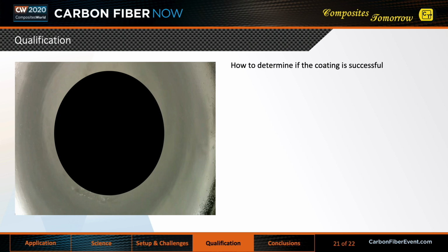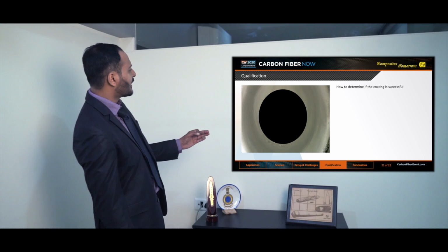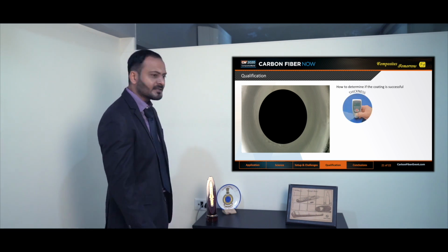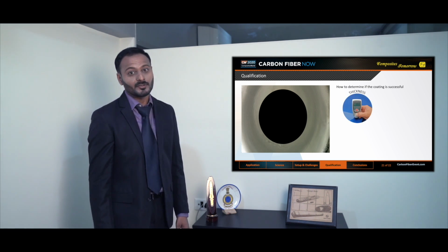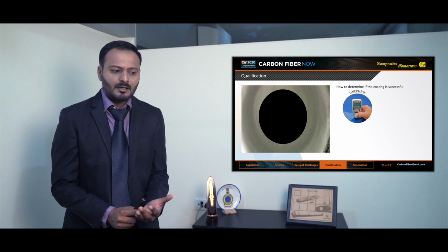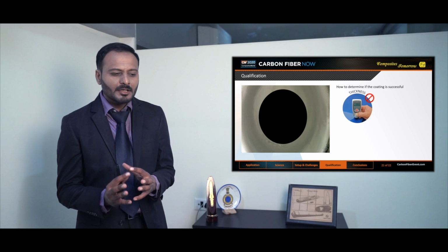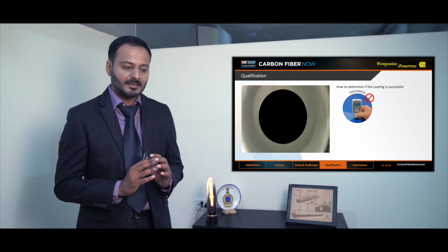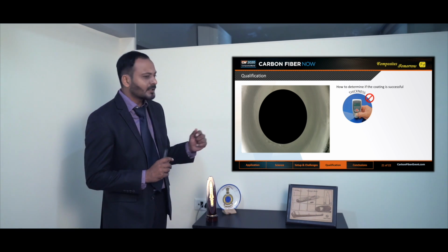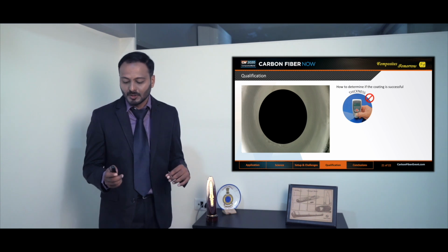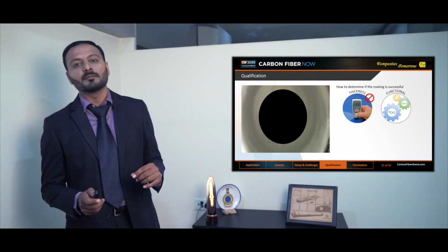Having sputtered the shell, having the wonderful coating around, how do I determine if my coating is successful? Do I measure the thickness? I would not suggest so. Reason, the thickness measurement technique is still not developed completely and may misguide you a bit. Plus, there is always a variation because this is just a nano thickness build up. The better way of checking will be a functional check.